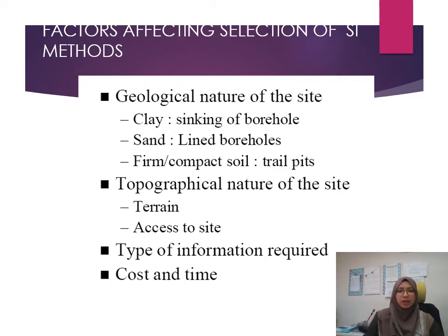And for firm or compact soil, you might use trial pit, together with all of the supporting equipment. And if you have rock material, you might use core drilling. So you can cut the rock, explore the rock, and also get the soil sample. Okay, number 2 is topographical nature of the site.